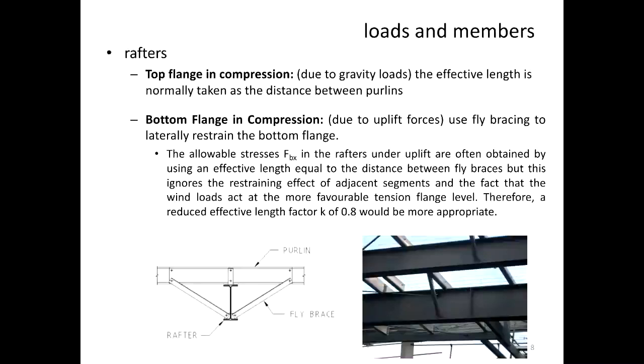Okay, so that's what that is saying. The fly brace? No, it's bolted to the gusset plate. So there's a gusset, you can see that gusset plate there. That's a gusset, not a cleat. That's a gusset plate there. It's welded to the beam. And then there is a hole in that gusset plate which receives the fly brace. Does that make sense? Okay.